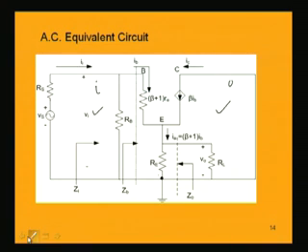Now, we can find the value of the resistance at the base to ground, denoted by Zb. Just to simplify the matter a bit, let us find out what Zb is. Zb is the input resistance looking from this point, between this and this point. That means it is the ratio between the voltage Vi and current Ib.